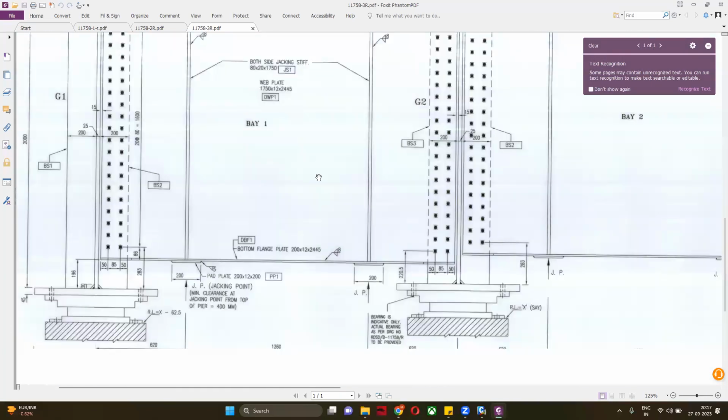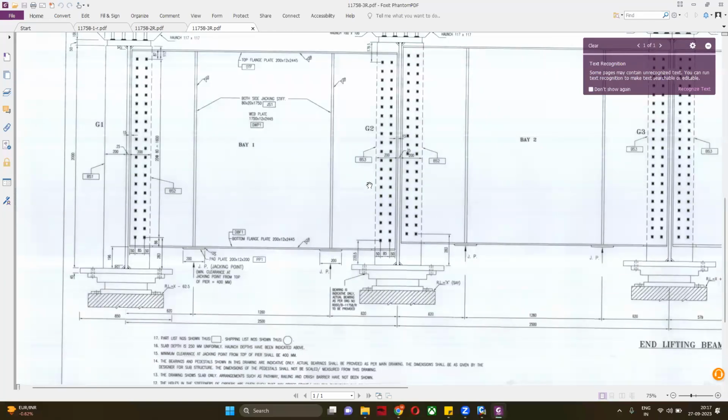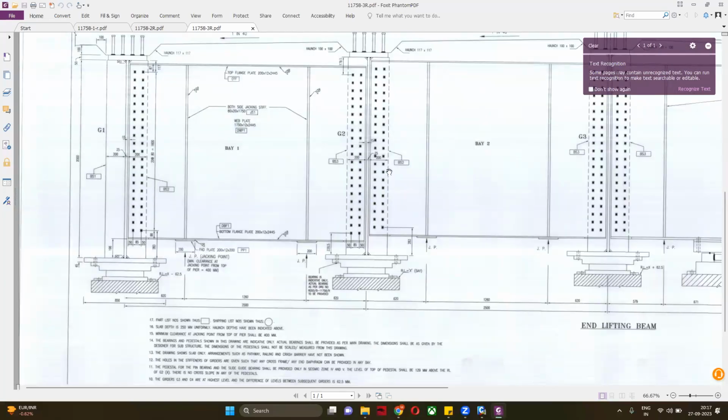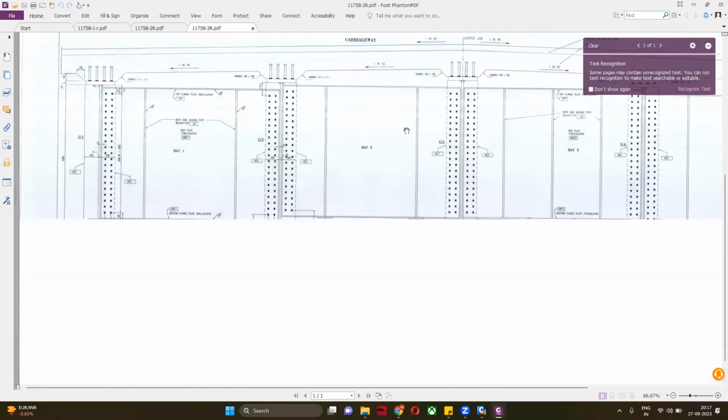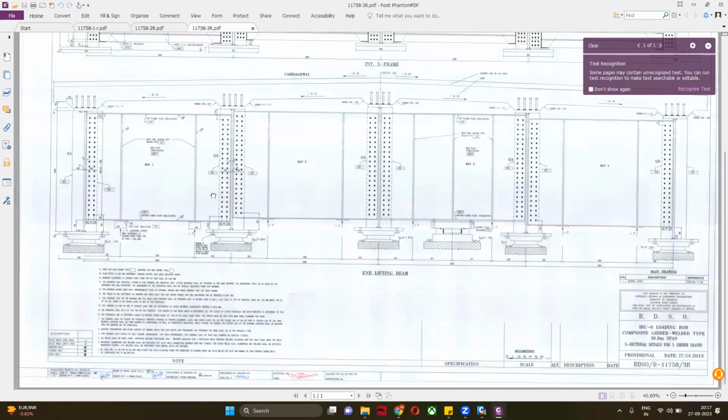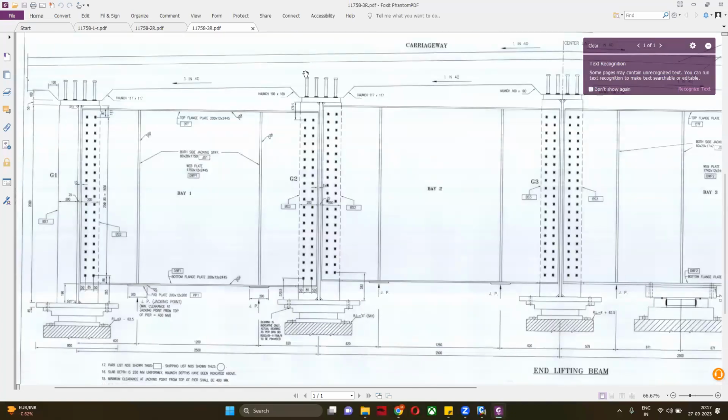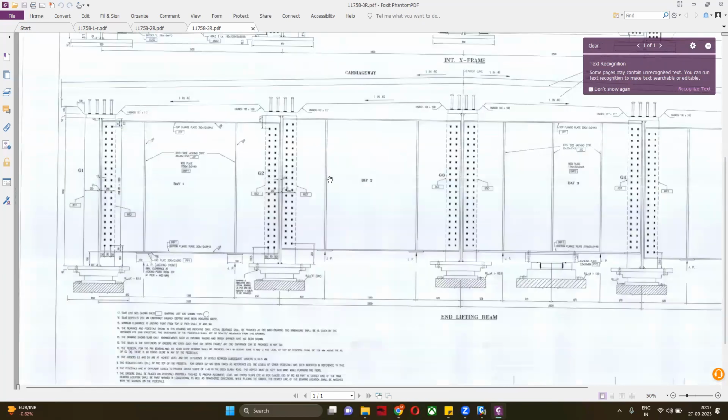Why? Because if you look here, the height is different. We know the pedestal height will be different due to the 2.5% slope we provide in our bridge. Due to that, generally these plates come at different locations in one girder than in another. But in our modeling, we can directly provide all at equal distance. You do not require to provide that. That is okay, sir. Yes, that is fine.